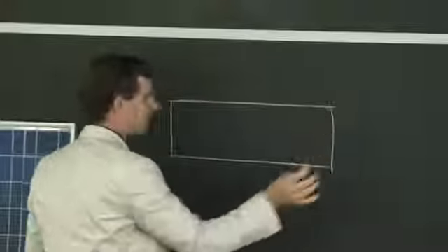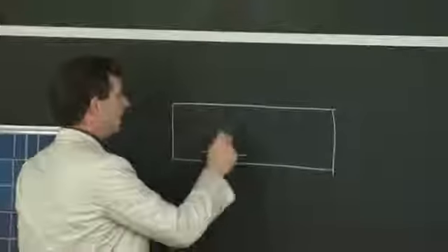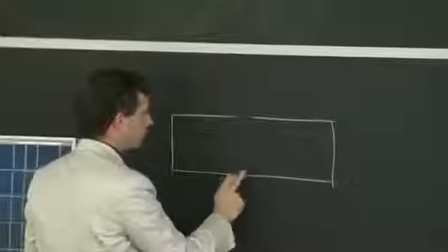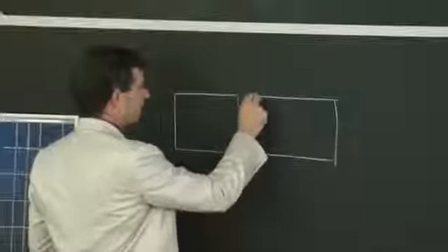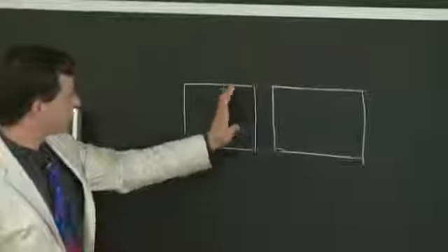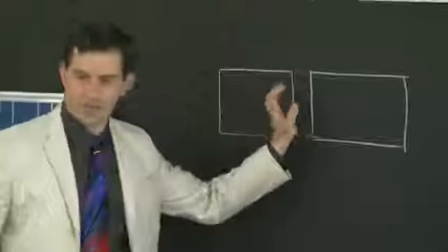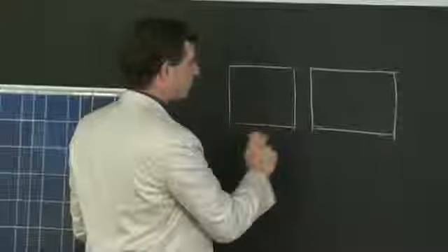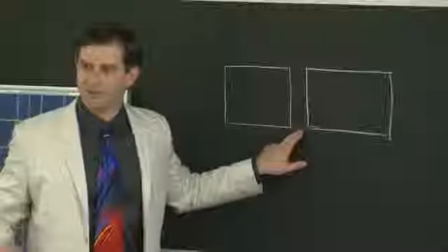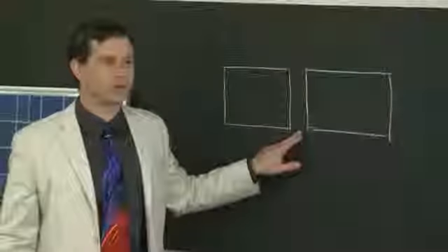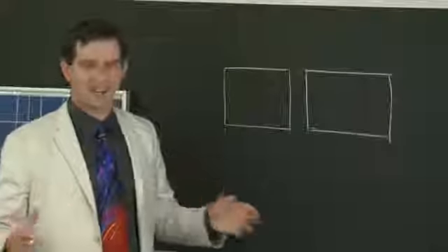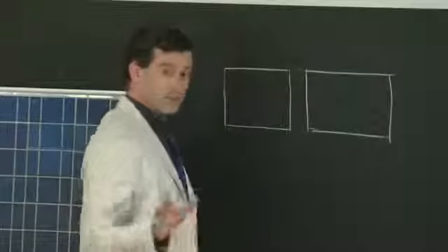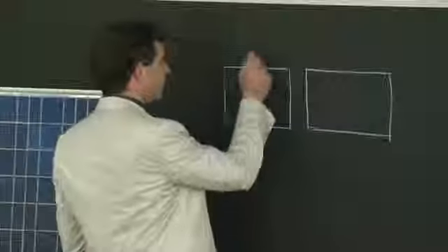You could add texture, but I'm omitting it just for simplicity. Now let's see, we drill a hole using a laser right here. So we have a very thin hole. Of course, in 3 dimensions, there's mechanical rigidity by the bulk of the material in the other dimension. But we have this hole drilled through, and we can make about 18,000 of these holes in about 6 seconds with modern laser technology. So it's really not that hard to make this happen, although a lot of engineering effort is put into it. But it is possible.